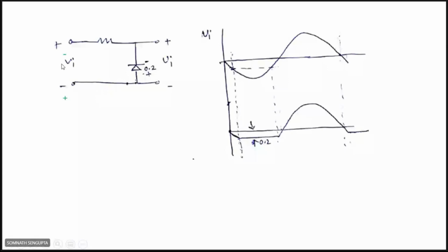Okay. So you see that it is a sinusoidal, alternating signal. For the first half cycle, this is positive and this is negative, and in the next half cycle, this is negative and this is positive. So this way it is changing. When the input voltage becomes negative, that time this cathode terminal will have positive voltage appearing on it. So we see that time it will be forward biased and the diode will be on.